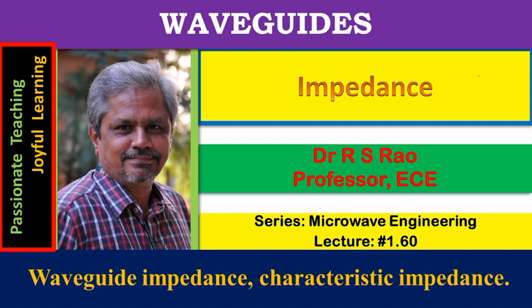In waveguide theory, we come across two types of impedances. One is wave impedance or waveguide impedance. Another one is characteristic impedance. The first one is useful in computing power flowing down the waveguide, whereas the second one is useful while providing load matching to the waveguide. In the present module, we focus on these two types of impedances, their expressions.